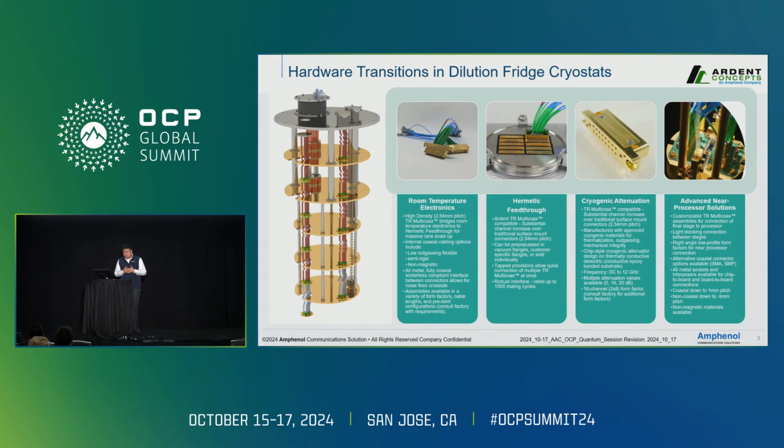While these control electronics come in variable form factors, from modular PXIe-style cartridge designs all the way to highly customized front panels, all of those solutions are geared toward maximizing RF connection points. Establishing microwave RF connections within the quantum computer relies on specialized hermetic RF feedthroughs. These feedthrough components maintain the necessary vacuum levels inside the cryogenic chamber while serving as impedance-controlled electrical transition points.